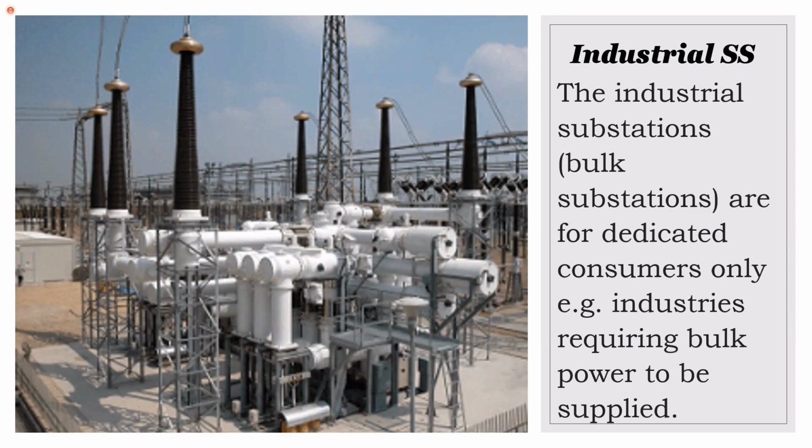lessons that you should have taken from it is that increased demand for reactive power would mean that there would be an increase in the apparent power. Everybody cool with that? Now, the reactive power demand would be coming from the use of motors and that sort of thing. Agreed?